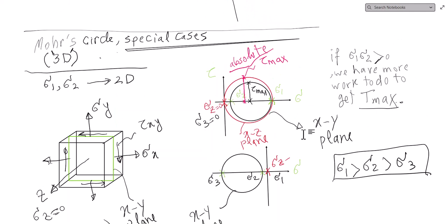And the beauty of Mohr circle is it is quick. It gives you the principal and maximum shear quickly, and it is very good for 2D. But when it gets to 3D and more complication, the analytical method, as we will be discussing, is much better. Okay, thank you.